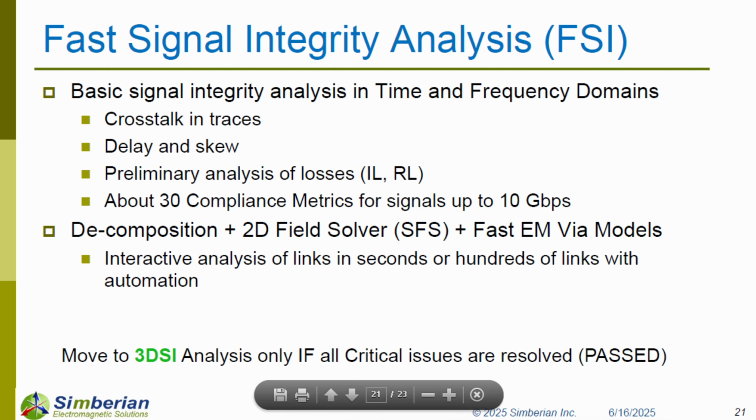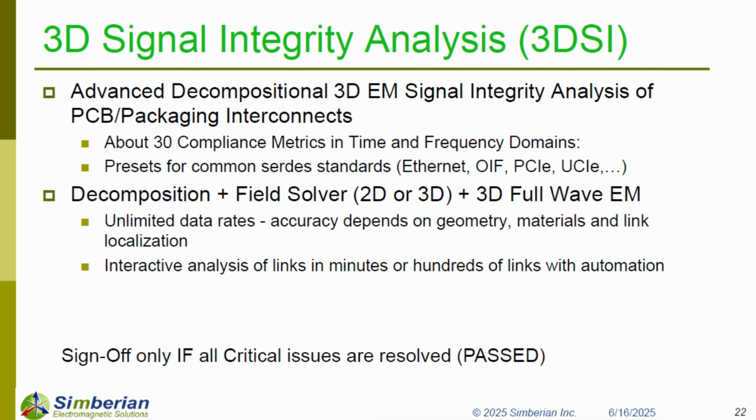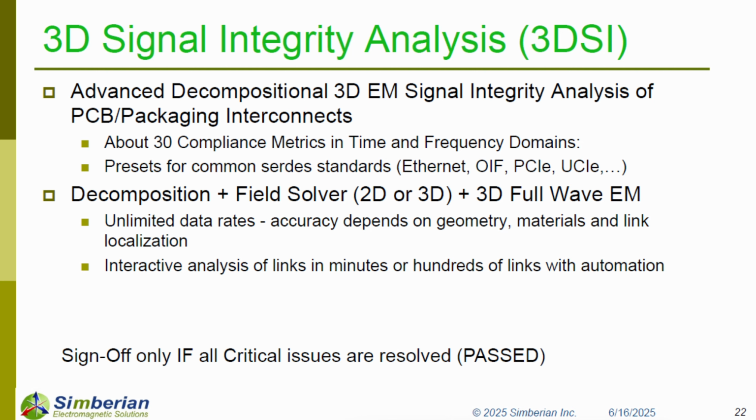It's more accurate analysis of return losses, but pretty much the same. The 3D SI mode in SI Compliance Analyzer is based on advanced decompositional 3D electromagnetic analysis, and there are about 30 compliance metrics that can be specified in time and frequency domain. And there are presets for common SerDes standards.